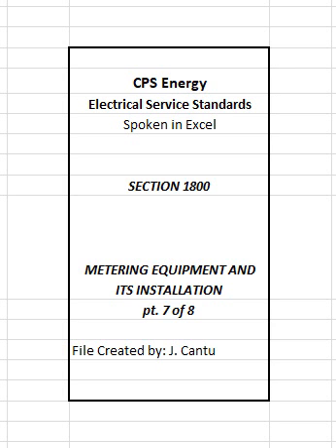1809 4. Connections to CPS Energy metering equipment. Customer-owned equipment such as generators or other voltage sources, load management devices, instruments, relays, etc. shall not be connected to CPS Energy meters or circuits in meter sockets or metering equipment enclosures except where specifically contracted with, and approved by CPS Energy. CPS Energy may determine the location, use, and wiring of such equipment, where necessary for safety, service reliability, etc. The equipment may be under direct control of CPS Energy, with customer access only as permitted by CPS Energy.